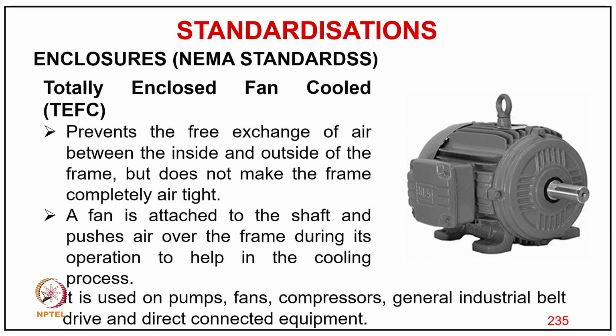Then you have totally enclosed fan cooled, called TEFC, which prevents the free exchange of air between the inside and outside of the frame, but does not make the frame completely airtight. A fan is attached to the shaft and pushes the air over the frame during operation to help the cooling. It is used on pumps, fans, compressors, industrial belt drives, and direct connected equipment.